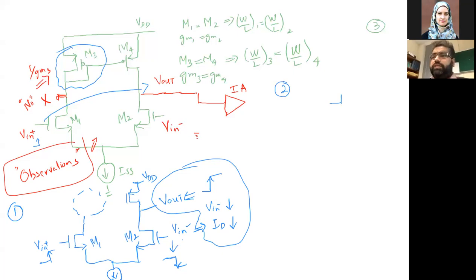The circuit is going to be, again, this is a PMOS for us. This PMOS is connected to something, VB, and this VB is going to be here. So that's another topology, and then this is a current mirror. This is just a reverse of whichever we have drawn here. Let's give any name, M1. Again, these names don't have any relation with the earlier names. I'm just writing some names to say these are some transistors. And here is some current I.